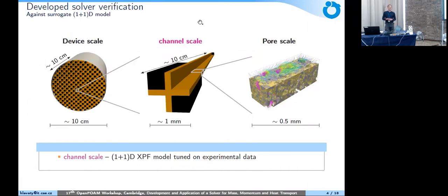Really interesting. And I have another technical question. How are you meshing the packed bed? How are you working with the contact area, especially since you work with heat transfer? Well, the packed bed is prepared by our group, which works in CFD-DEM and so on. They prepared an STL file of the bed for me, and I used snappyHexMesh to create the mesh based on the STL file.